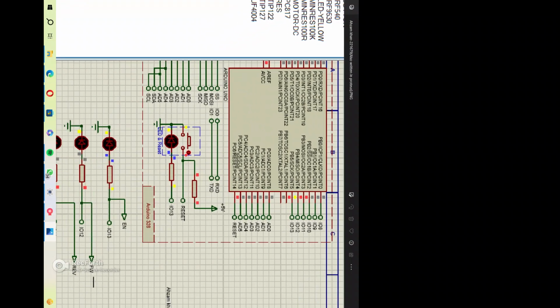Conclusion: the use of an H bridge in DC motor control is simply an easy way to control the direction and speed of a DC motor. The real challenge lies in choosing the integrated circuit and power supply related to handling the voltage and current the motor will draw, as I mentioned previously.